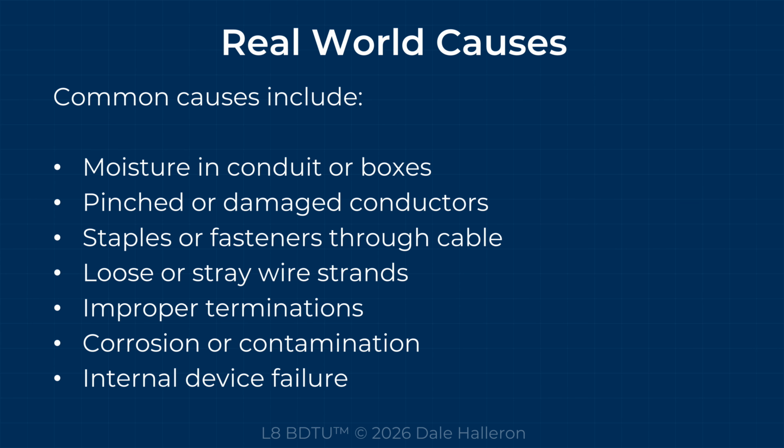Real-world causes. Common causes include moisture in conduit or boxes, pinched or damaged conductors, staples or fasteners through the cable, loose or stray wire strands, improper terminations, corrosion or contamination, or an internal device failure.